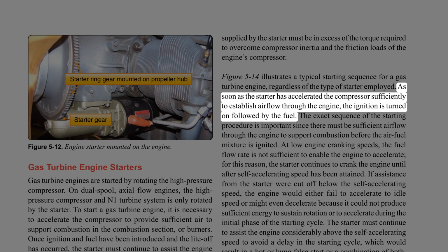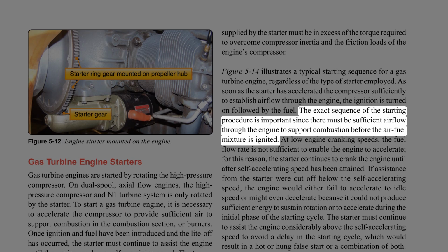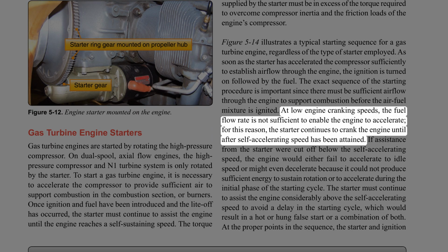As soon as the starter has accelerated the compressor sufficiently to establish airflow through the engine, the ignition is turned on followed by the fuel. The exact sequence of the starting procedure is important since there must be sufficient airflow through the engine to support combustion before the air-fuel mixture is ignited. At low engine cranking speeds, the fuel flow rate is not sufficient to enable the engine to accelerate. For this reason, the starter continues to crank the engine until after self-accelerating speed has been attained.